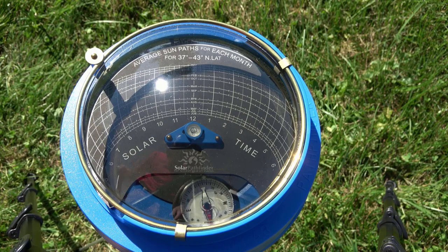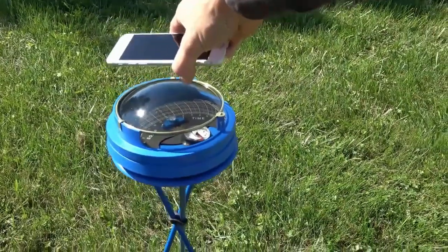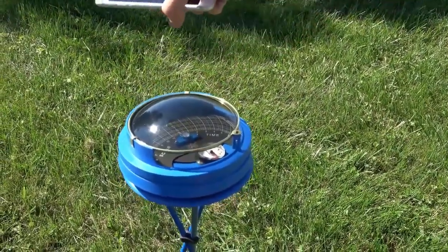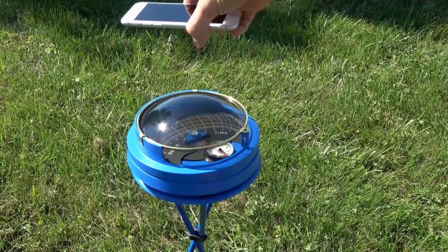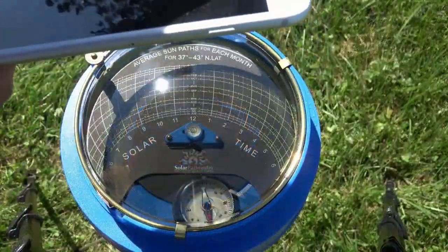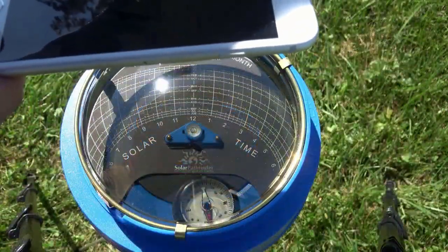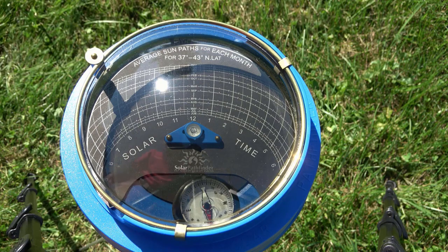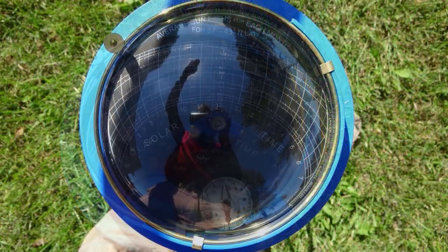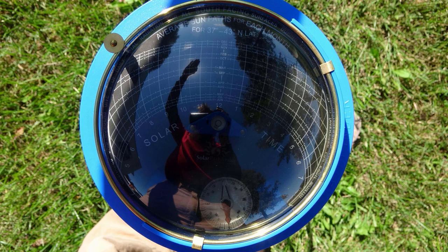We can either trace an outline of the objects that are reflected on the dome, or we could simply take a photograph from above. In any case, we can see when this location will be shaded or exposed to potential sunlight through the year. Shading occurs at any time that the reflection of an object intersects with the sun paths on the diagram. In this case, we have a shadow that's being cast on the location every morning from the building that's located on the east side, meaning that we won't have much sunlight at this location until sometime between 7 and 9:30 a.m., depending on the month of the year.